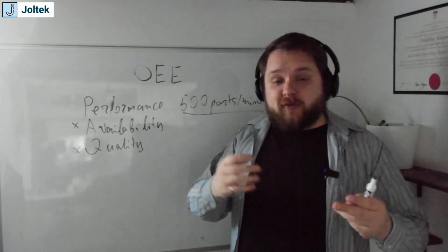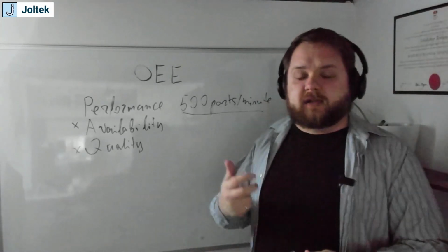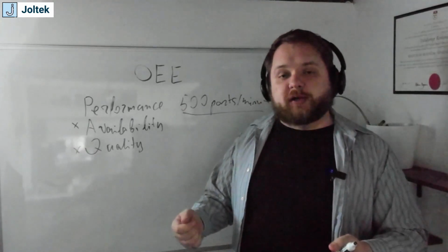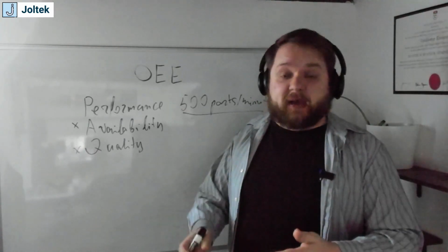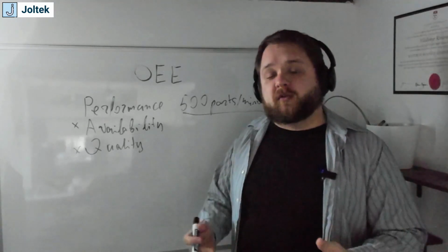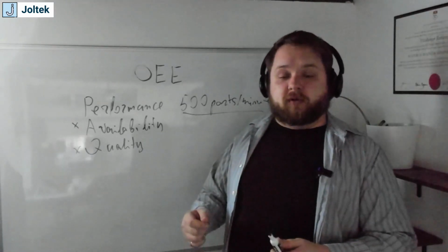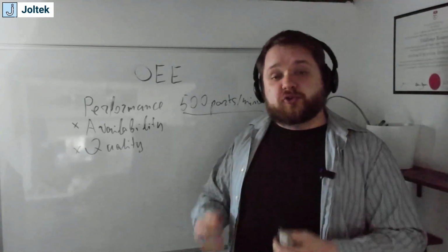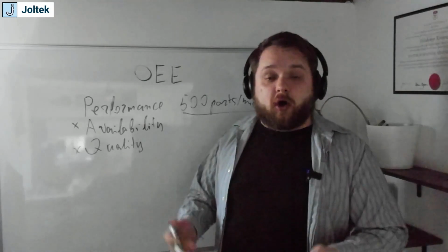Therefore, it's a lot easier to send that data into a system that's going to capture that count, versus, for example, a batch that goes through an entire cooking, ingredients, then maybe fermenting process, and then at the end there's a manual quality check that rejects the entire batch for a specific step. At that point, it becomes a little bit more difficult to track. So if you have the ability to capture the data at the machine level, in most machines you'll see a reject chute, and you should have a counter that will tell you how many parts have been rejected on a basis.